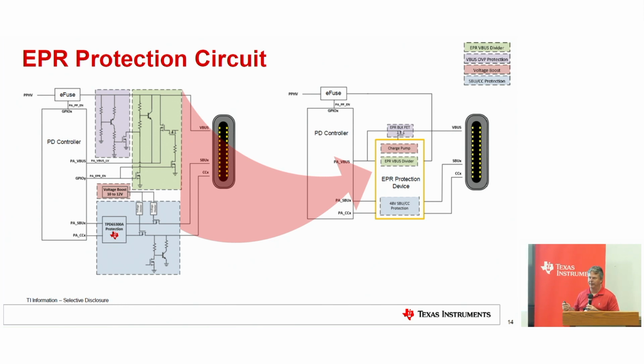That would be bad. So the comparator would automatically engage the divide network to keep our chip safe. It's a safety circuit to keep from over-voltaging devices.